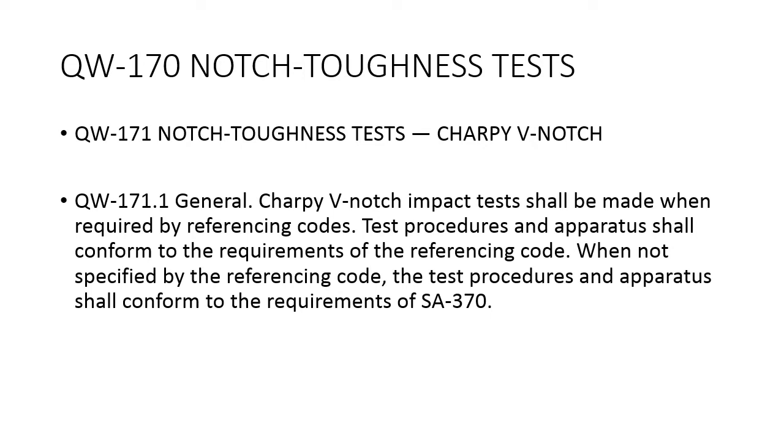But generally, you don't do notch toughness testing unless the engineer calls it out, the qualifying code calls it out, or the construction code that you're referencing calls out this notch toughness testing.